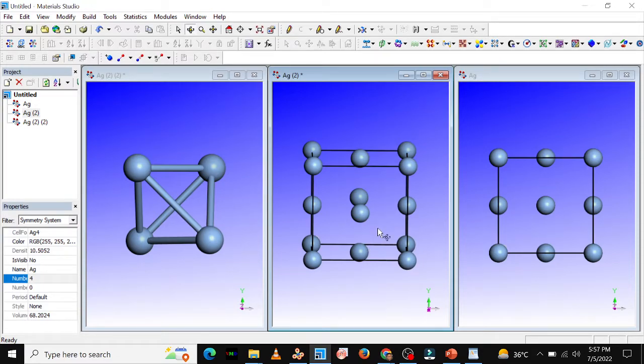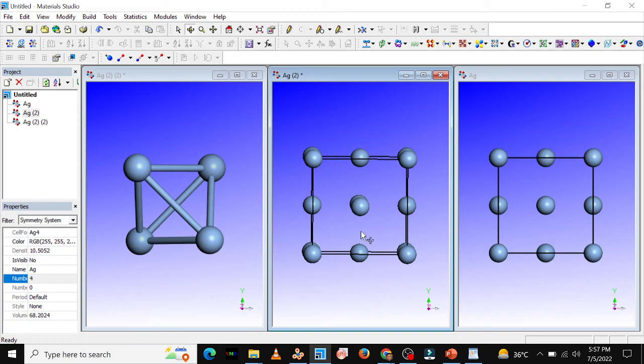Okay, and here this is half, so 1 and 1/2, and this is half, so 1 and 3/2, and this one is half of contribution. So from the side it is half of contribution. You can see this is half, this is half, this is half, and half is outside. So the total number of atoms in this unit cell, this is basically the unit cell, is 4.